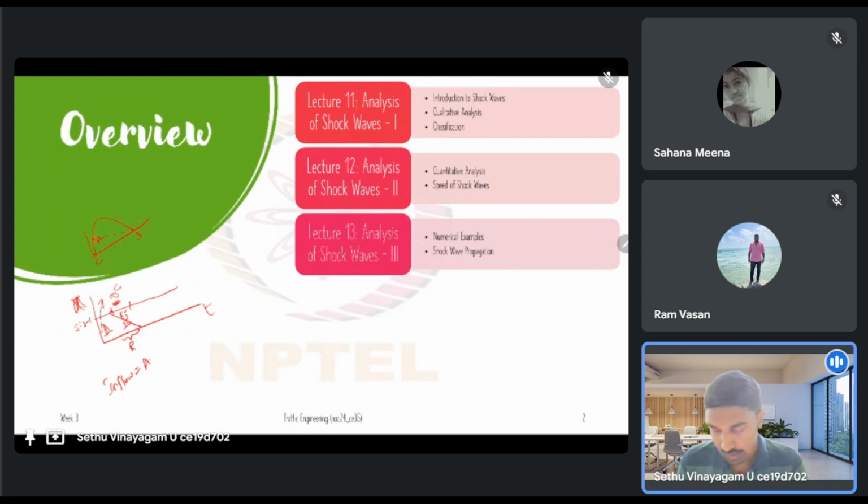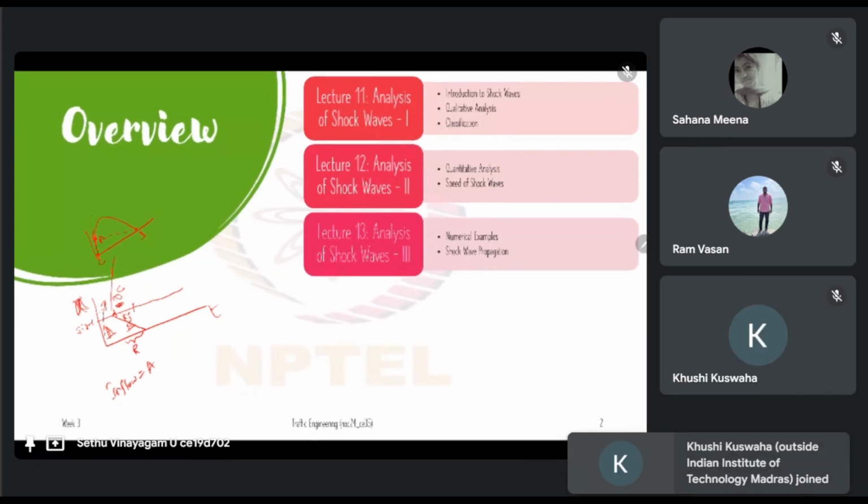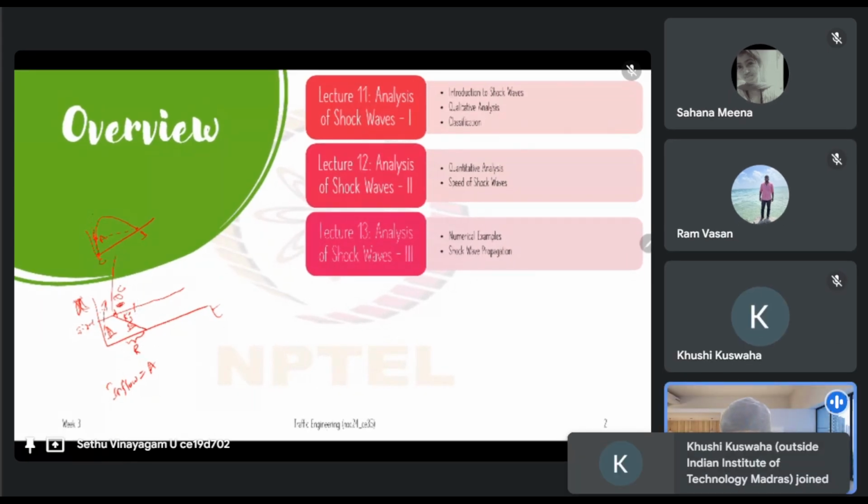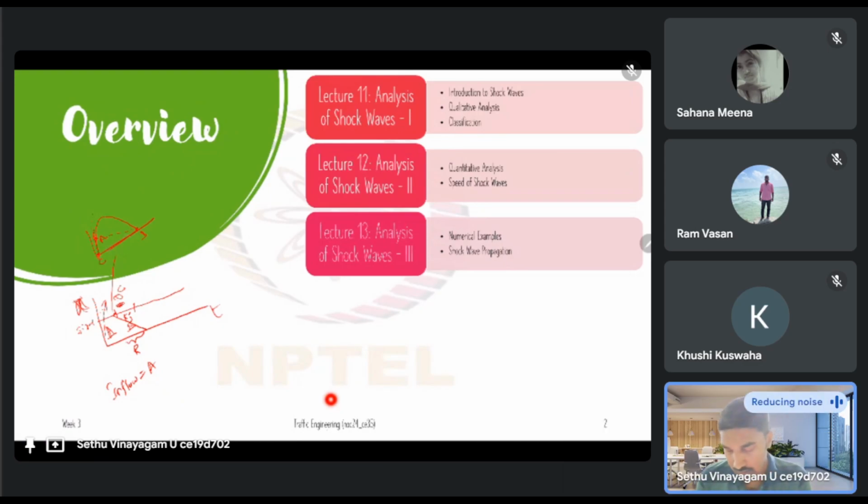And what will be created between A and C? A and C will be at this particular free flow speed, so this is at some speed. Then you also have B and C. What is the traffic state between B and C? It will be a horizontal line, right? When you join B and C, it is a stationary shock wave that will be created.